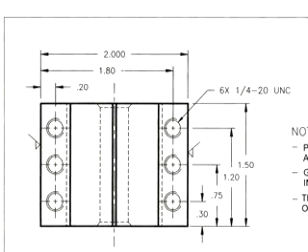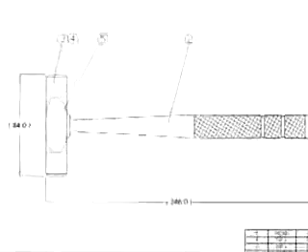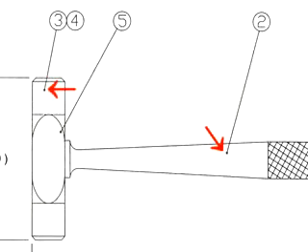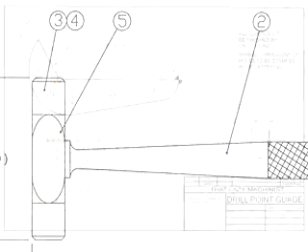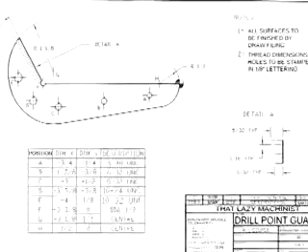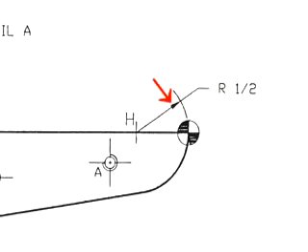When we use a dimension line that only goes to one side, it's not called a dimension line, it's called a leader line. And again, they attach a dimension to an entity. But be careful. If the entity is represented by a line, the leader line ends with an arrowhead, as is the case here. But if the leader line points to a surface, then it ends with a point.